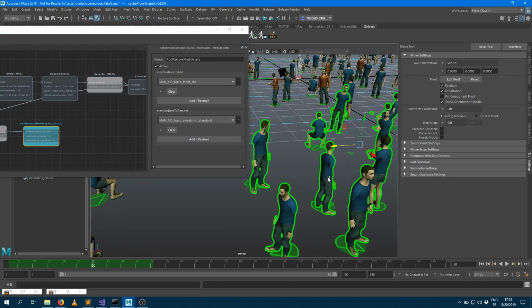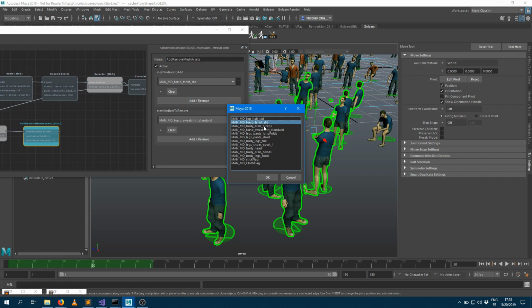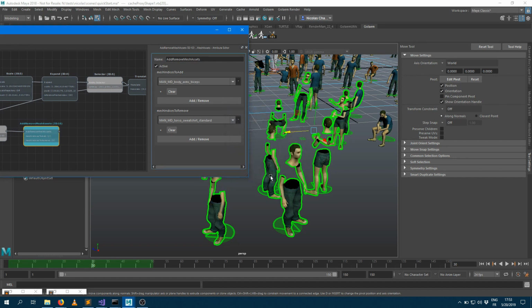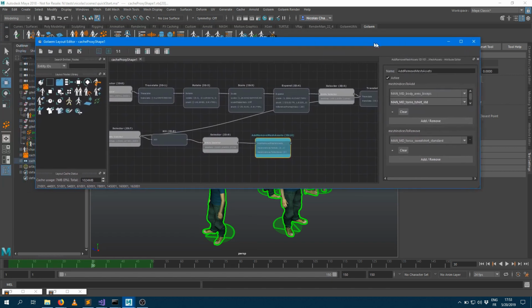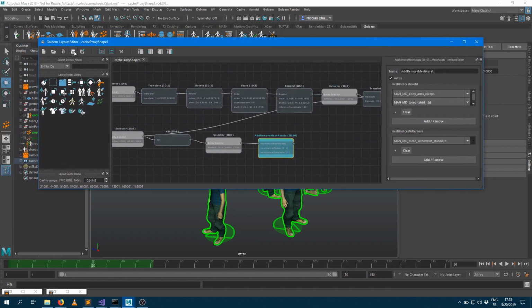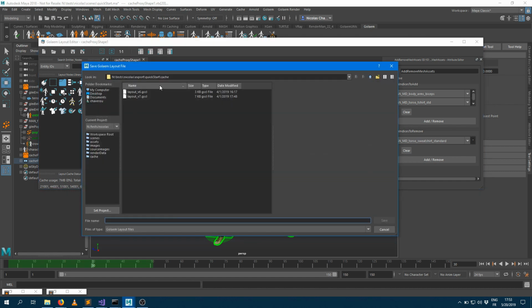Here the t-shirt is made, but if I want my characters to be complete, right now they don't have forearms, so I also need to bring the forearm meshes, like the biceps meshes, and press OK. Oops, sorry, I want to add another one into the list and say this is going to be the t-shirt and the forearm. And whenever I'm happy with that, I press save here to save that file into my quick start. So let's save this. That file is a JSON file.